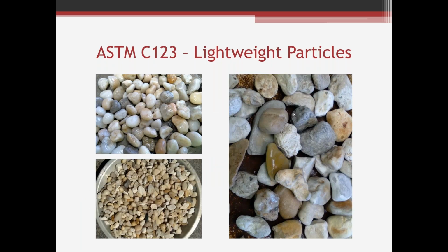And I think it's easy to understand why you don't want lightweight particles in your concrete. You don't want them to float. A lot of times lightweight particles are lightweight because they're porous, they've got voids, and they're just generally not very durable to be put in concrete.